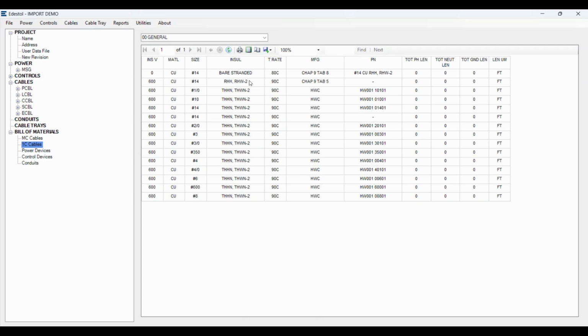This is where it didn't reset the ground and the neutral for us. But you've got part numbers, manufacturers, and distance for phase, neutral, and ground if you wanted a green and a white wire. All your different sizes are shown there, and your distances would be set had you put that number in there.